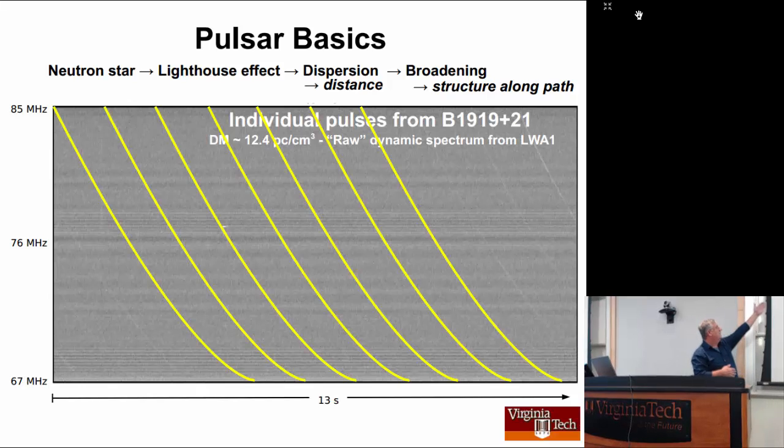And at these frequencies, you can see it very clearly. You see the high frequencies arrive early, but that pulse gets stretched out, so you see a chirp instead of a pulse. So if you just try to detect this and you're not clever, you just do total power and you see nothing because all the pulses overlap. All right? So what you have to do is a process known as dedispersion. Dedispersion, I'll explain in just a moment, is the undispersing of this. So you get regular pulses and you can do regular traditional impulsive pulse matched filtering.